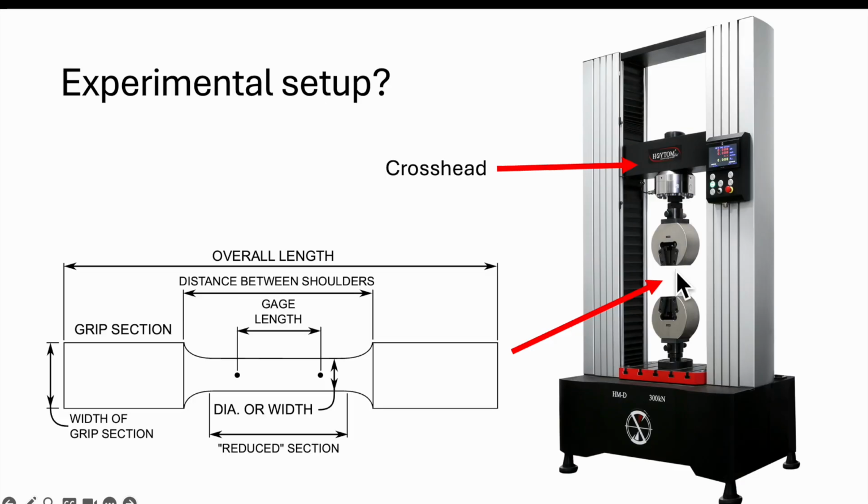So what happens is the extension or displacement in all parts of the system are collectively measured. So inside the gauge, but also this region out here outside the gauge length is also extending. The grips can extend. The grip itself can move. There can also be extension in any sort of junction that we have.